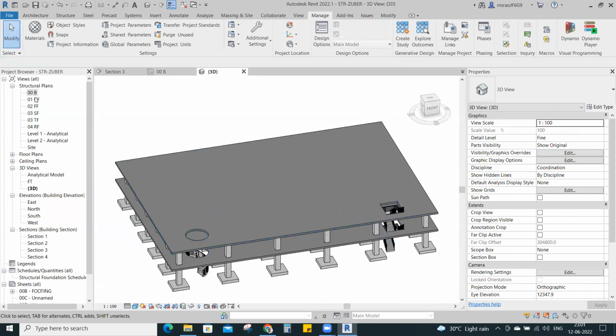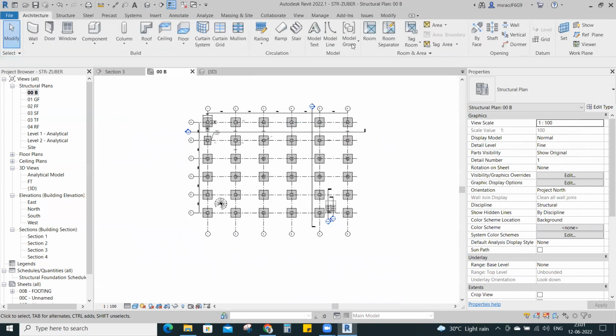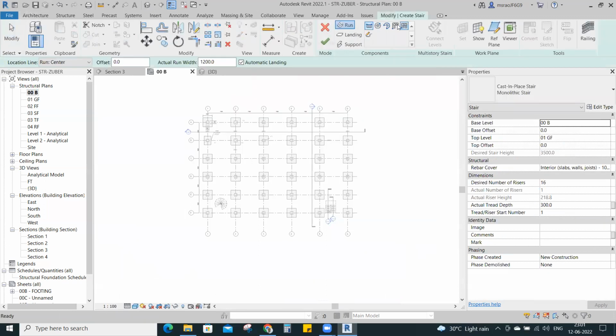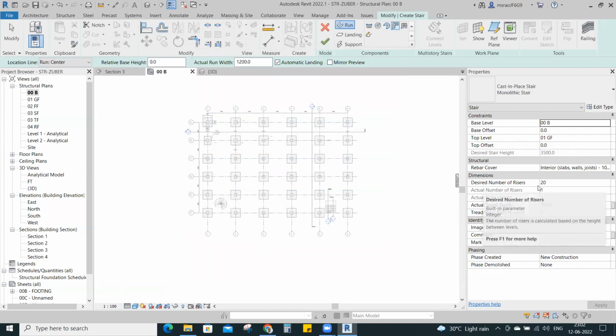Shaft and stairs. Let's say, for example, I want to use one more kind of staircase. Select winders. If I take the winder, it's a predefined one. If you go to properties, we have to manage. Let's say I now want to use the riser at 175 mm, tread is 220 mm and width is, let's say, 1200. Apply. So now the riser changes to 175.